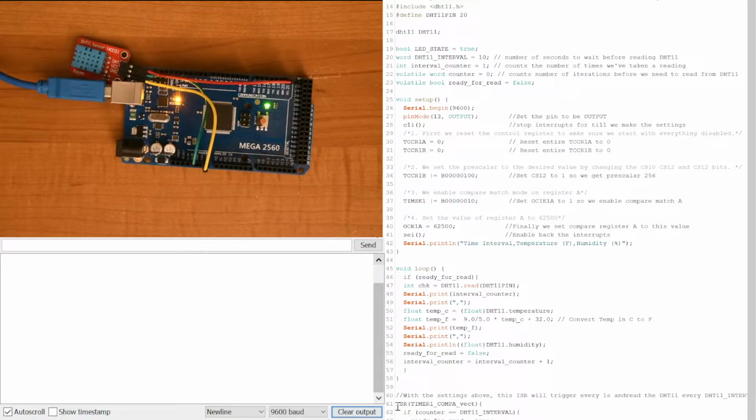So then kind of going over the ISR now. The logic here, since our interrupts are limited to a 1 second interval, just due to the limitations of our values, specifically we can't cleanly hold a value larger than 1 second here because, for example, if we did 10 seconds, which would essentially just be this value here, that exceeds the size of our register. So we can't hold that there. So we just go with the 1 second interval and loop through right here with this counter.